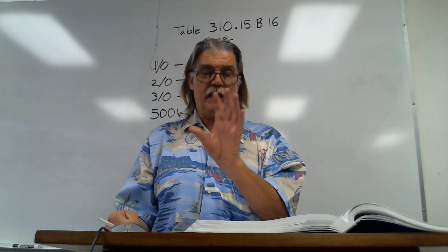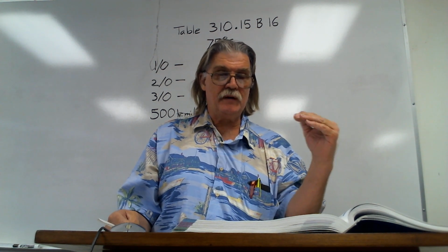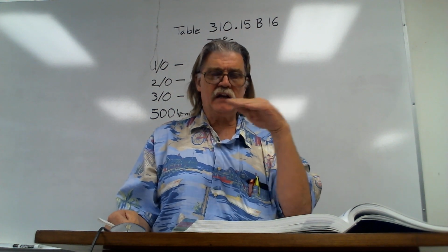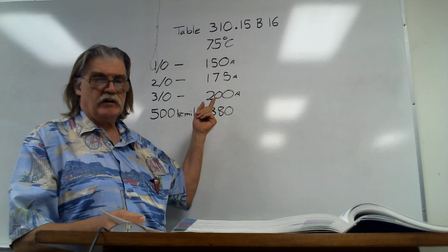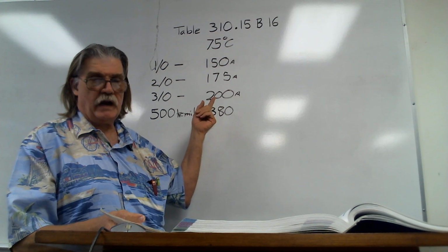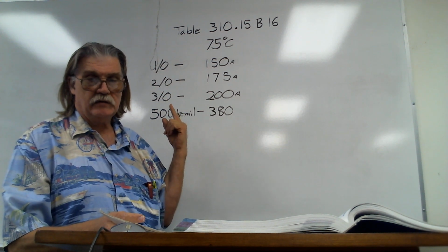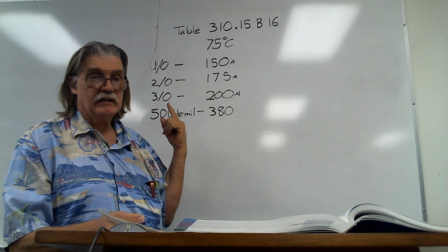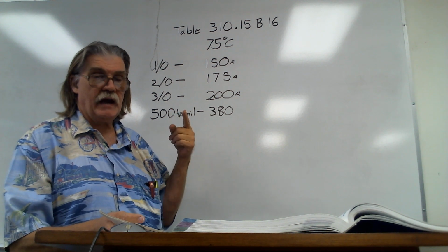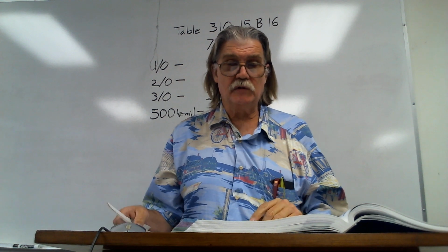Okay, so if you've got the size of the breaker, go down one, get the minimum, look at it. As long as there's not a conductor at the same value. Like if I were to say, hey, on a 200 amp breaker, what size wire? Well, 3/0 is rated to 200 amps. You would have to use 3/0, okay? You couldn't use a different one because there is one that matches it. Okay, hopefully that clears up those two rules for you.